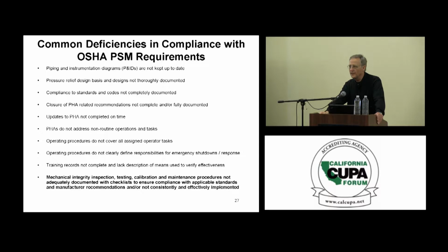So that's another thing. When you put in these controls, you've got to be able to get to them to activate them. Piper Alpha North Sea oil rig disaster in the 1980s. They couldn't get to the deluge system. They'd put it on manual control. The fire started. They couldn't get to the control panel to activate the deluge system. Lost the whole rig and 180 people or something like that.